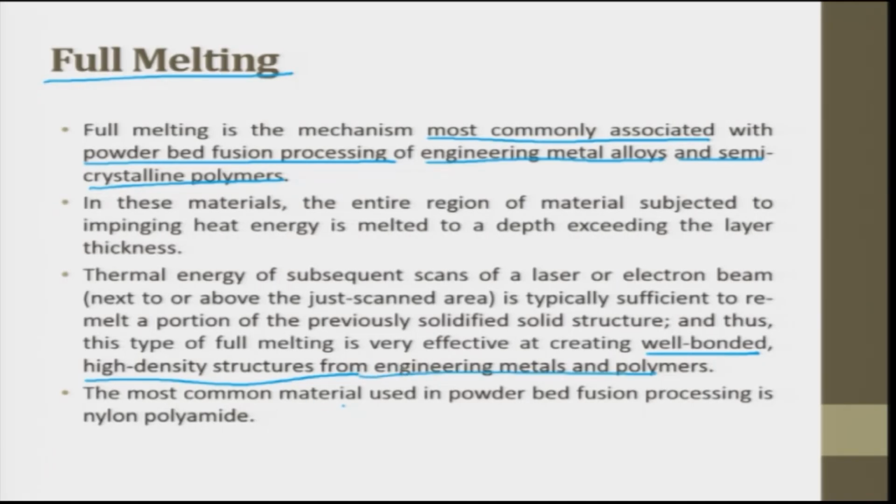The most common material used in powder bed fusion processing is nylon polyamide, wherein the entire region of the material subjected to the impinging heat energy is melted to a depth exceeding the layer thickness. So, if your layer thickness is this, now the laser hits, so the heat goes up to here. What will happen? You will have better stitching of layers. If it is having better stitching of layers, delamination will be very less.